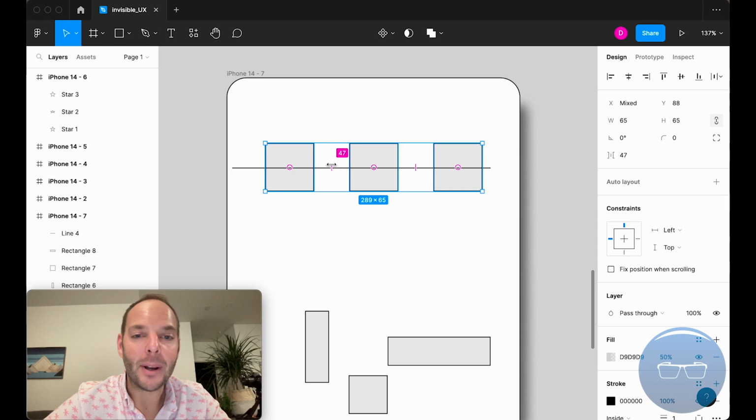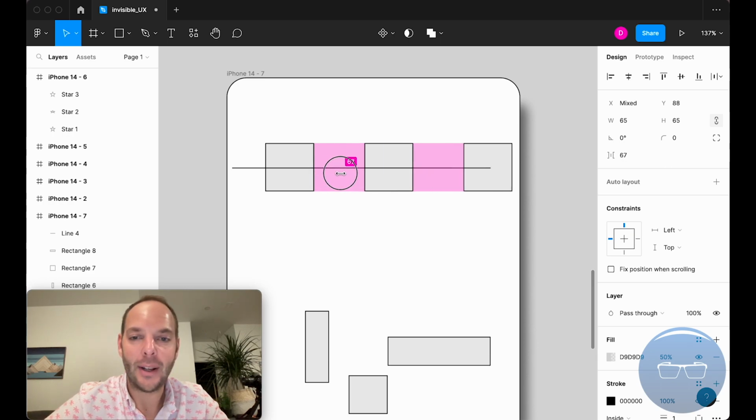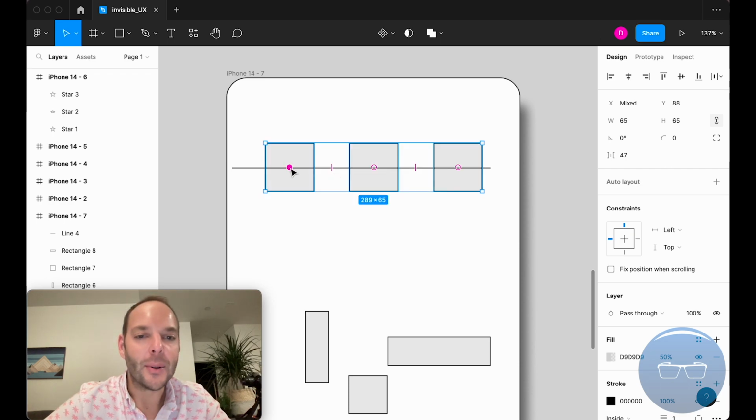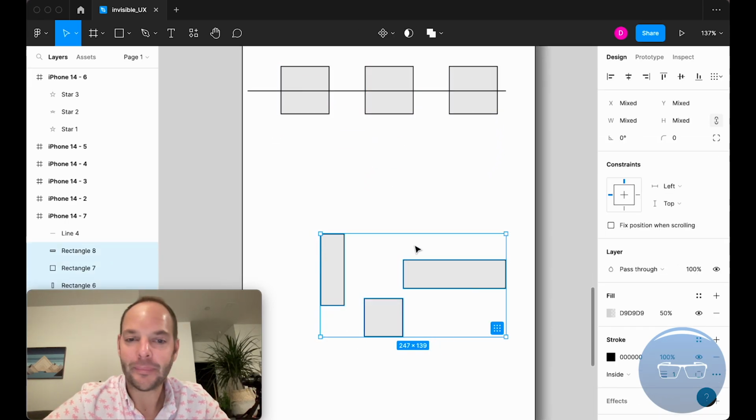And you can confirm that because since there's an equal amount of space, you can hover over this line and that actually tells you how much space there is, right? Another cool trick that you can do with these lines that only appear when there's equal space between objects that are selected, you can grab it and adjust the spacing between all objects simultaneously, which is pretty cool. You might also notice these circles here. So this is getting a little bit out of the scope of the exercise, but let's go ahead and dive into it. But this is better illustrated with objects of different sizes.